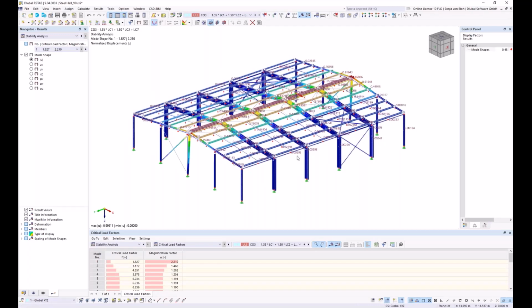As a part of the stability analysis evaluation by mode shape, the mode relevance factor can be used to quickly differentiate between local and global mode shapes. A modal relevance factor of 100% means that a single member has maximum relevance for the considered mode shape.